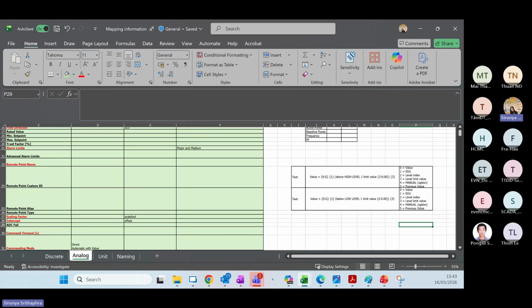Actually, we will send the signal from our ADMS, not from the device. Okay. Yeah, we can choose the protocol based on the project need, like we can use ICCP or Modbus also. But at this moment, you decide to use IEC 104 from your ADMS to send the signal to DERMS. Yes. Okay.